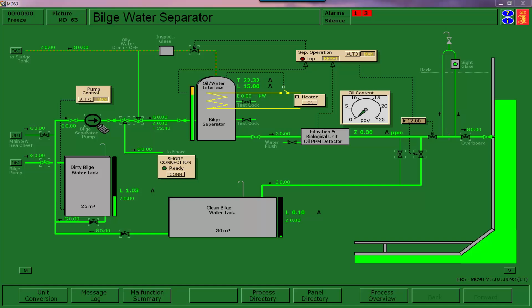Once you switch to bridge control, they will maneuver the engine out, and your role then shifts in the mid part of this exercise to monitoring the engine and its operations. And then once you are near departure, your role is going to shift again, where what you are doing is getting the ship ready for departure and shifting over your electrical loads to the steam turbine generator and the main engine shaft generator.